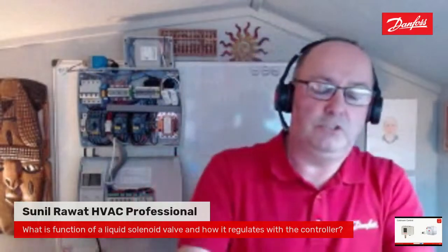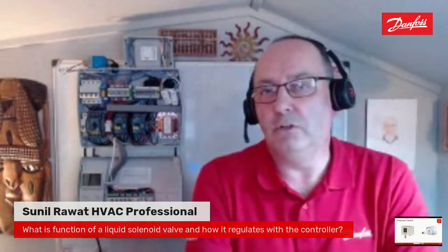So another question from Sunil: what is the function of a liquid solenoid valve and how does it regulate with the controller? We'll come to that as we go through the slides. Basically, there are two options regarding a refrigeration system. You can either pump the refrigeration system down using a liquid line solenoid valve, or you can literally stop and start the system. I'll go down a couple of slides and we'll talk around that, if that is okay, Sunil.